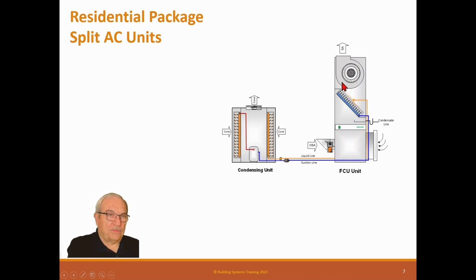So what happens here is we have an air handling unit inside. It draws return air, puts it through the filters, through the evaporator coil, out through the fan and out, and that's the air situation. We have an outside air intake that brings in ventilation air sometimes,